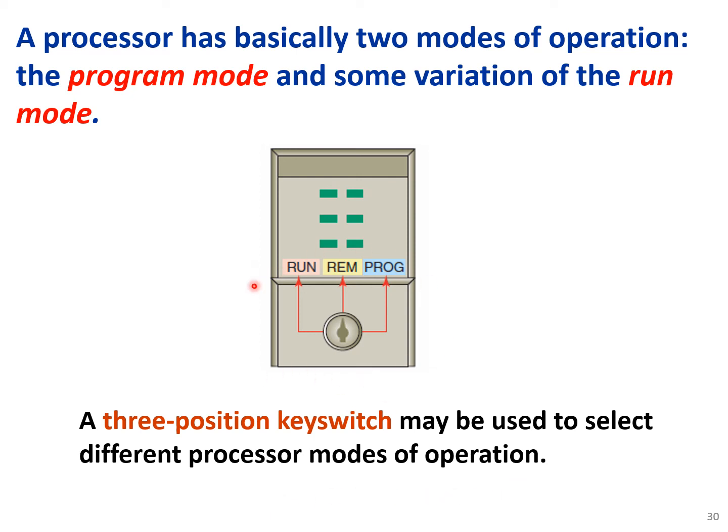You might not see the exact configuration on Siemens PLCs. Basically you could have, for example, run, memory, stop, and some other configuration that shows troubleshooting and communicates to the operator what's going on in the program. But this one is just an example based on Allen Bradley's PLCs.